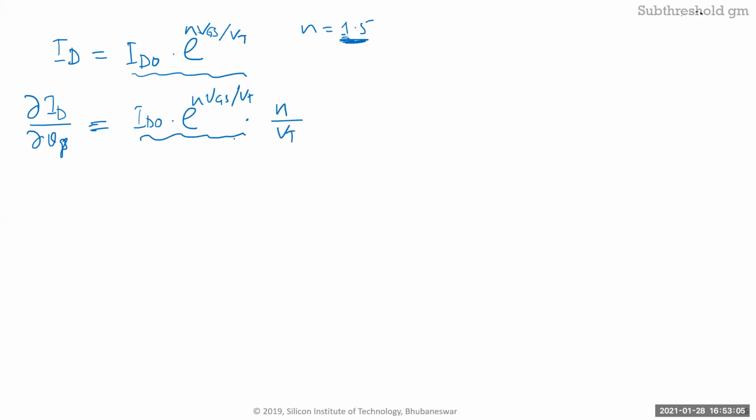And this is your DC bias, right? So this is ID over N VT. Where did we get this number? That was the diode small signal model too, which is actually the same as BJT.